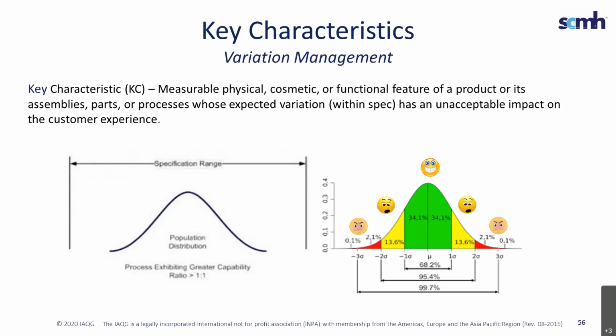And the little chart on the bottom right hand side is trying to illustrate this. As you move down in the standard deviations or up in the CPKs, you are increasing the excitement of your customer. The end user of the product can feel the variation reduction. And that is absolutely essential for defining a key characteristic.